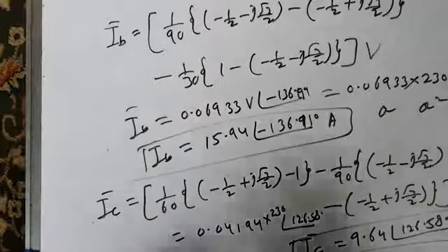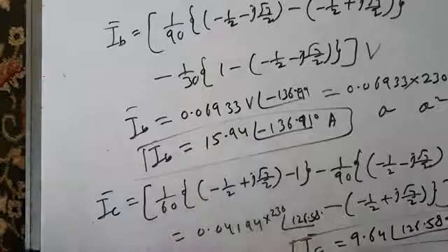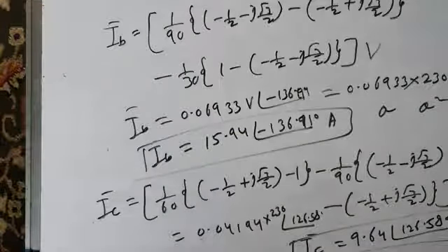In fact, later on we took a delta connected unbalanced load and solved it. How did we solve it? We transformed it into equivalent Y connected load and found the new equations for neutral to neutral voltage, and solved it same way, and we solved a numerical example based on that.